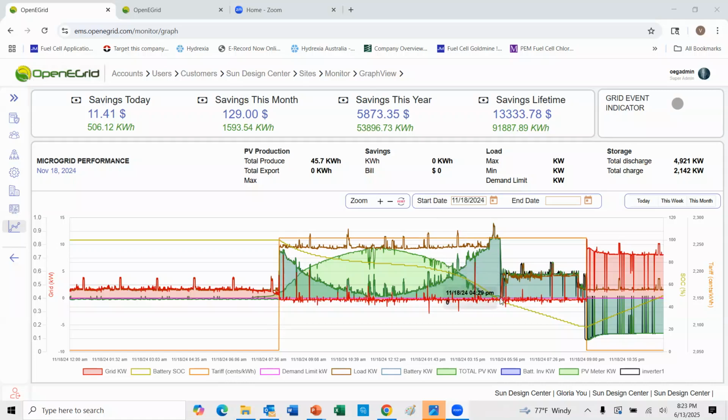So the battery is almost now completely supporting the load, and that goes on all the way until these people finally decide to go home, which is about 8:30 or so in the evening. The showroom shuts down. Batteries start to back off, and at 9 o'clock, when the tariff really comes down back to earth, then the system kind of heaves a sigh of relief, and the batteries now start charging up because electricity is cheap and you can draw power from the grid again.